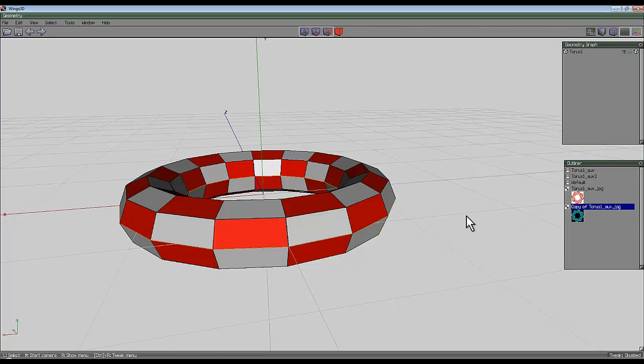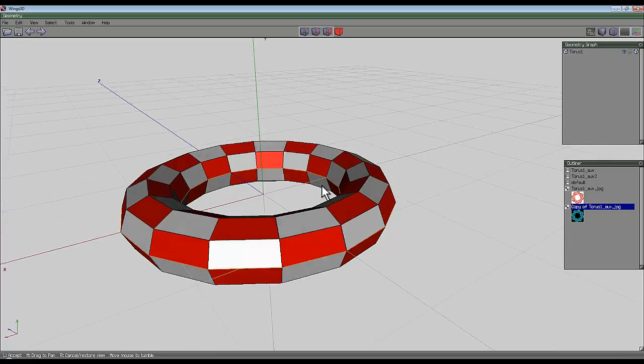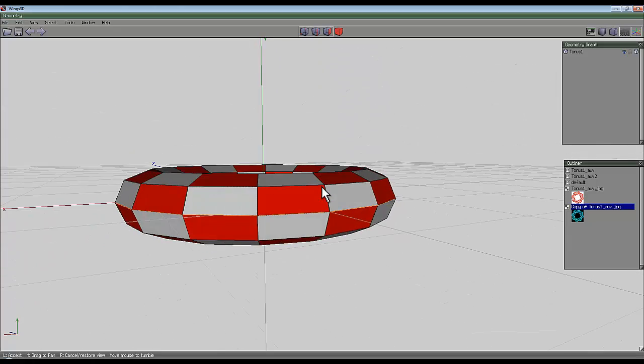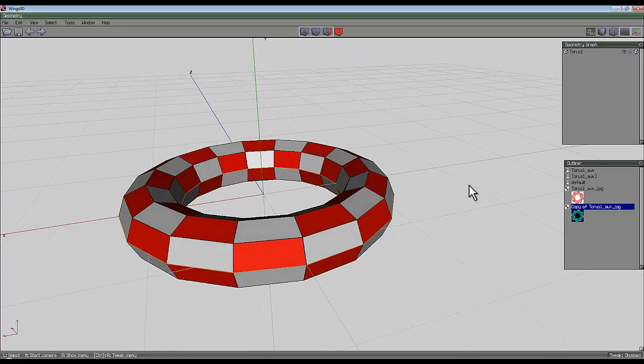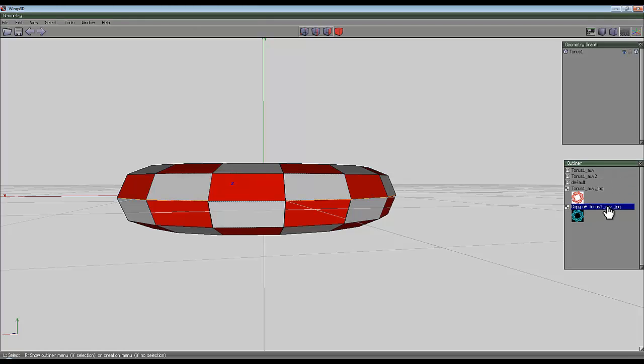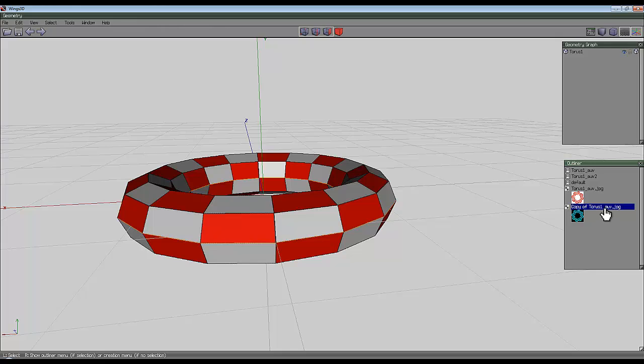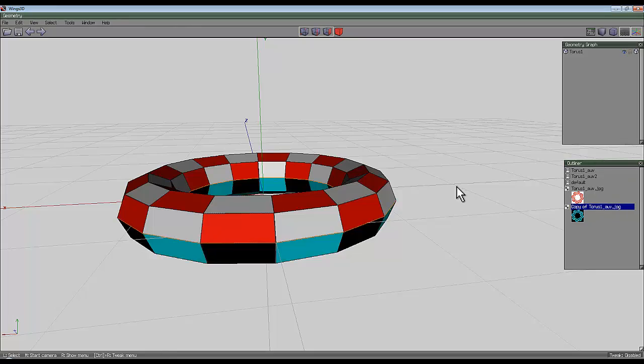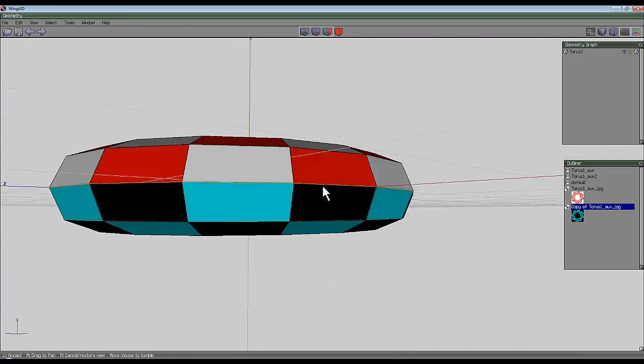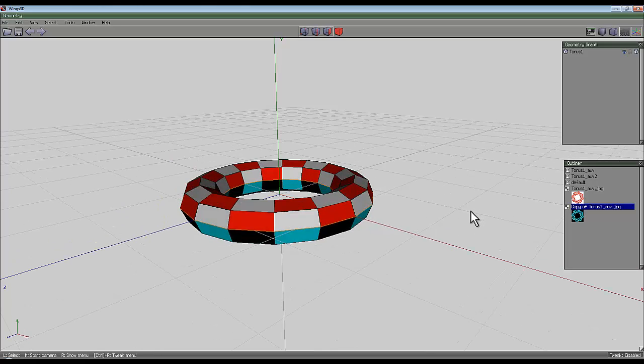And then if I refresh that, you can see that it's not had the effect that you might have anticipated. You might have thought when I copied that and copied that, it would automatically have made this copy apply to that material. But this map is the one associated with that material because I duplicated that and that was the case. To get this applied to the new material, I need to drag and drop it over and select diffuse, and there you go. You get the expected result. So that fooled me quite a few times.